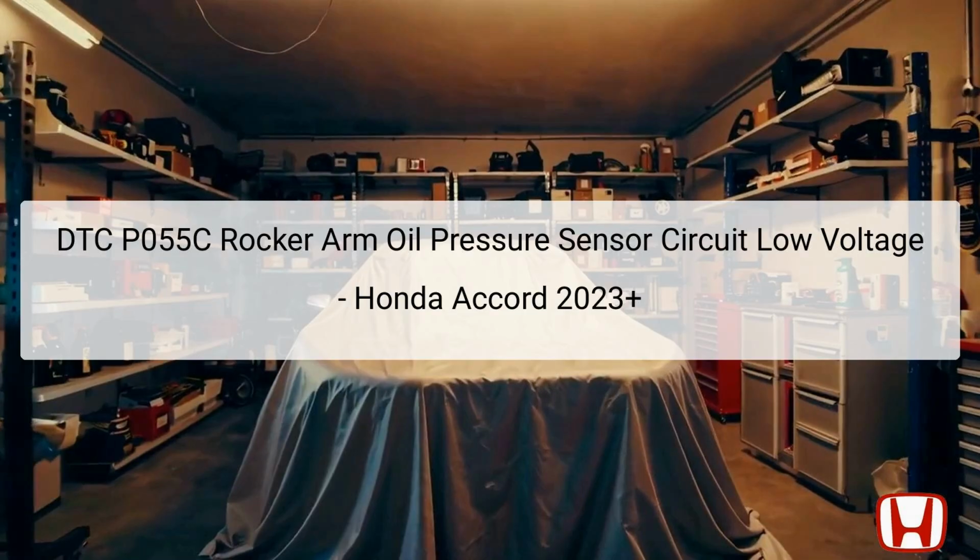If the PCM registers that this voltage is below 0.18 volts, it interprets this low reading as a failure condition, leading to DTC P055C being stored. This code is particularly important for maintaining engine health and performance in the Honda Accord 2023 and newer models.